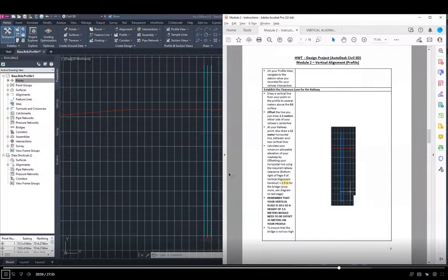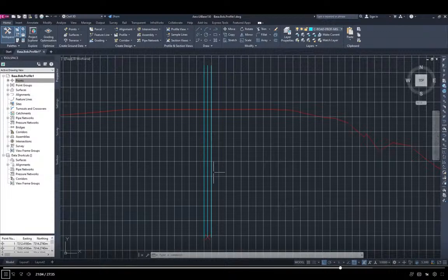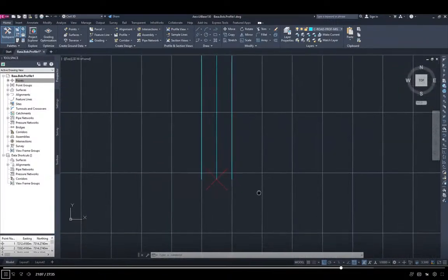At your rail point, now we want to draw the 12-meter horizontal line between those lines. It has to be centered here. I'm just going to draw a horizontal line. Remember, you can keep your ortho on, and it'll make sure that everything's vertical or horizontal. The ortho mode is right here. So I'm just going to create a line. I'm going to start at the node, making sure node is selected in your OSNAPs. I'm going to go to the right, and I'm going to type 6. There we go.